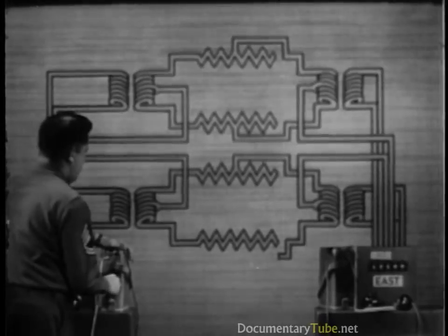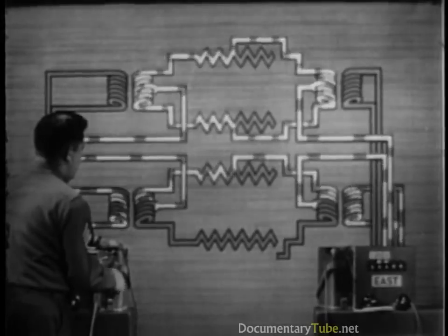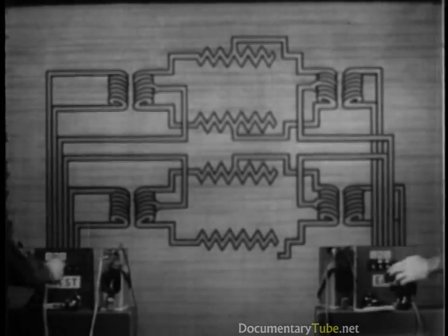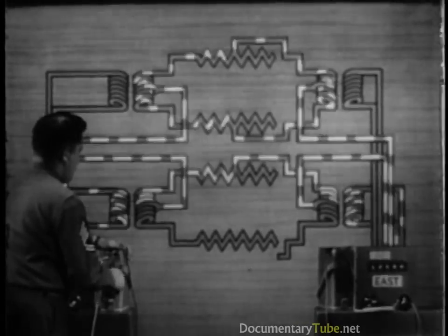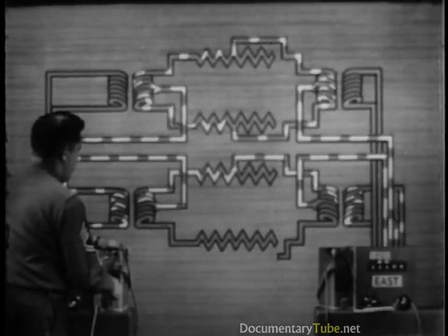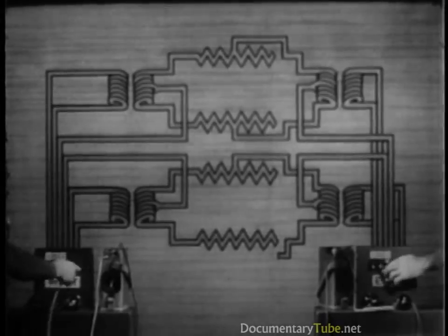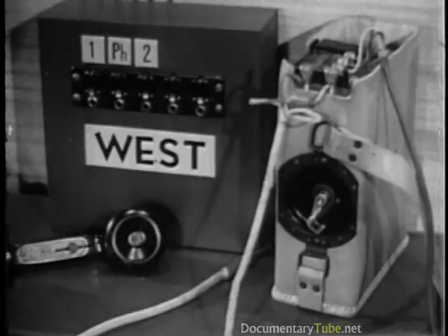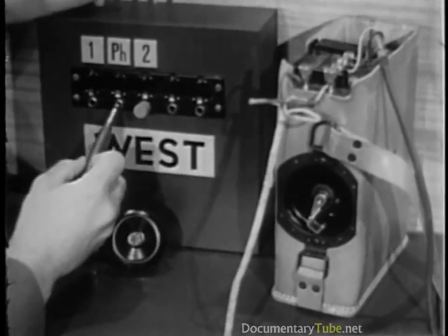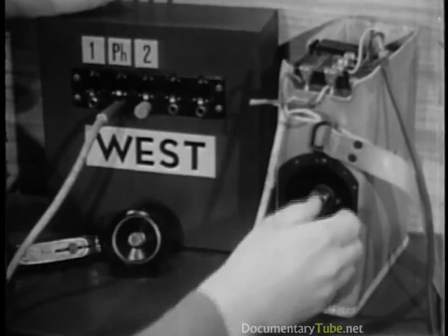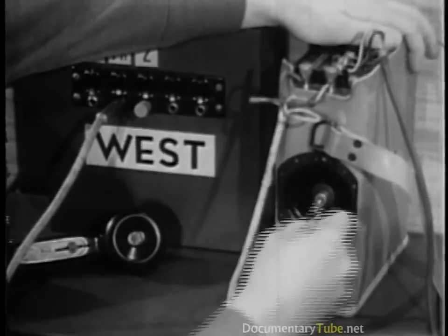The phantom interferes with the open side circuit and the open side circuit interferes with the phantom. If we discontinue the use of one, the other will not be subject to interference. Which one should we stop using? Well, transmission in the open side circuit is weak, so we eliminate it, and the phantom will work okay.